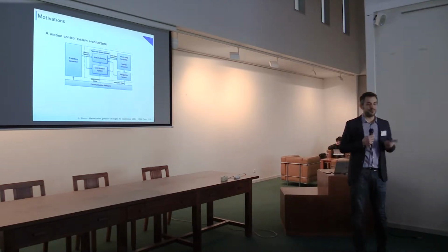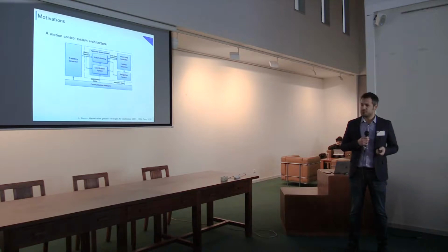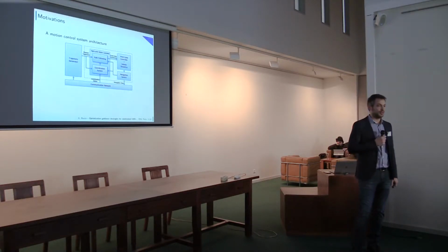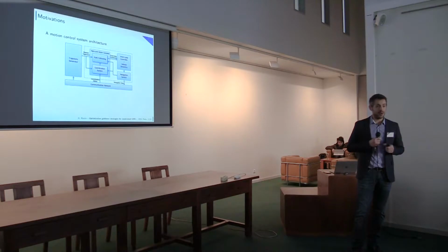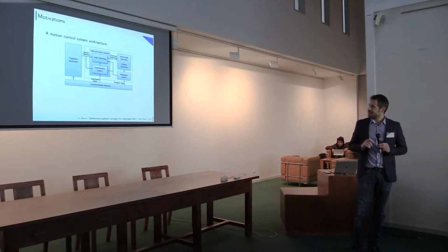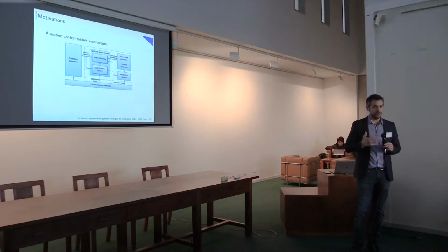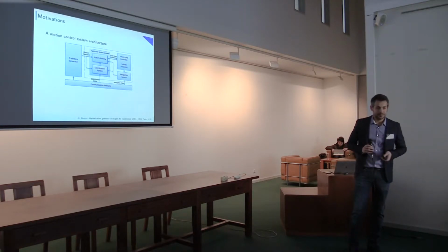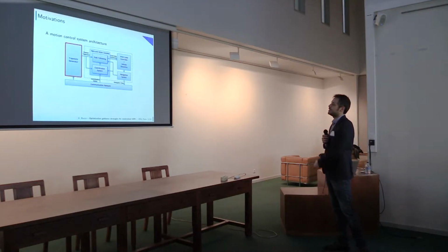This is actually the motivation of my PhD. I started playing around with a race car, using a tool called ADAMS, and I saw that it implemented just a simple PID controller, and the vehicle with a virtual driver was able to track a path, the center line of the track, but it was really, really stiff. Like it was accelerating, braking. I was able to see some oscillation of the suspension. But if you really compute a trajectory of your system that satisfies the dynamics, you can see that the vehicle is more comfortable with its own dynamics. So you can increase the performance of your system. So this is the motivation.